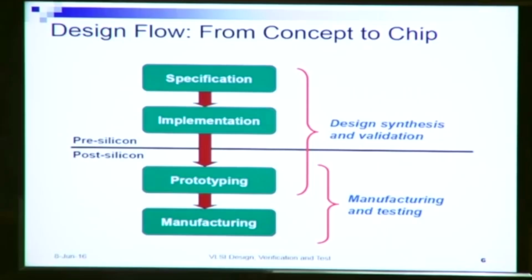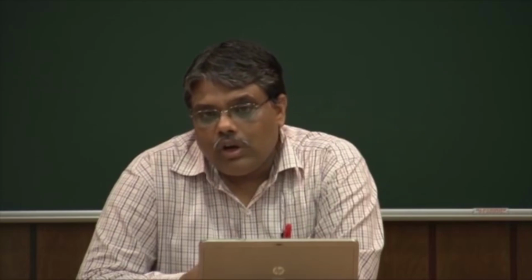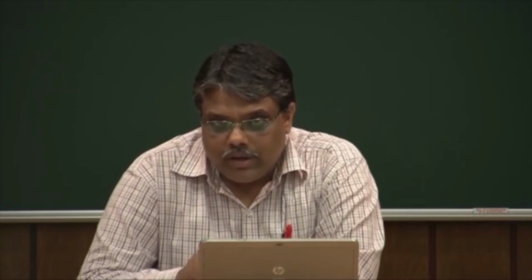Also, after we have prototyped, we have to see that the prototyped chip is error free. That means the prototyping process has the implementation taken care of all the issues. We have to test it. Testing means that on the implemented chip we drive certain test vectors to find out whether there are faults in the chip, right? So that is called prototype testing.